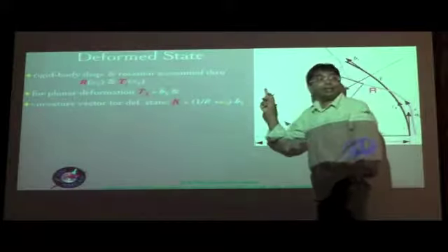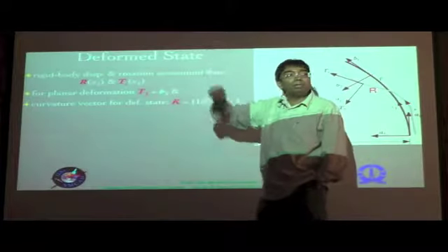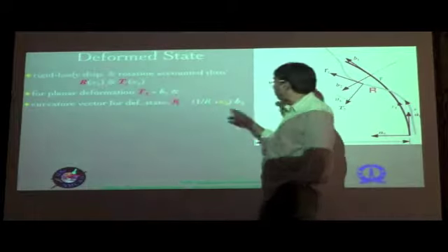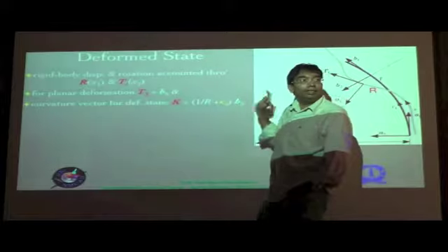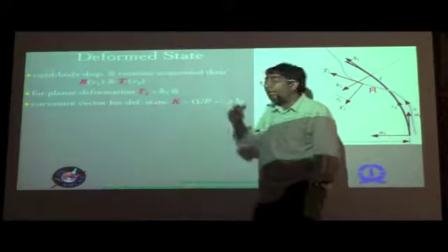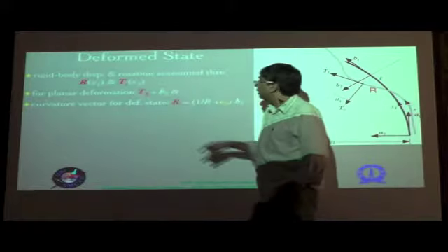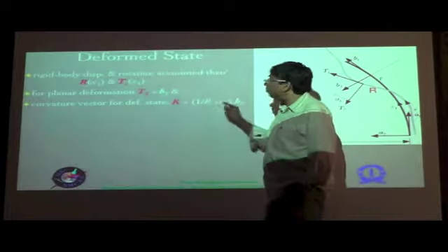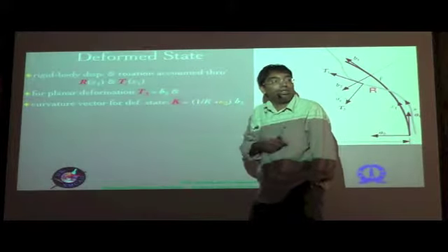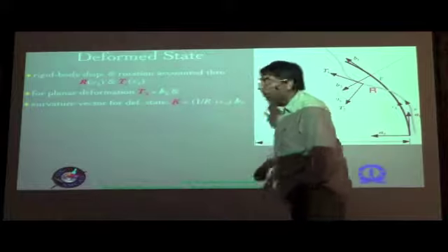In this case it is K3 because remember that big K always has to be in the big T system, or if we are talking about the big B system. But in this case, the big and small in the 3 direction alone have this correspondence. So in reality, this should have been T3 in a general case. Because of this simplification, talking only about planar deformation for this pedagogic example, T3 gets replaced by small b3 utilizing this particular equation. Otherwise, these two would have been in the small b system and this would have been in the big B system. This we have discussed in the vector dyadic definition for the elastic curvatures or the total curvature earlier on.